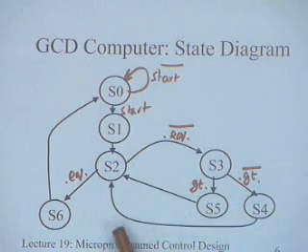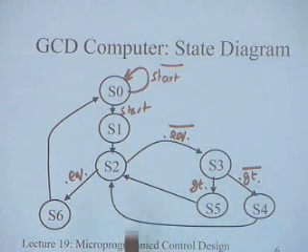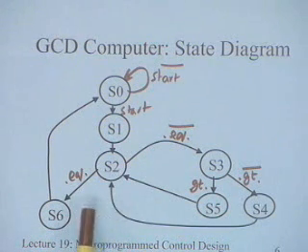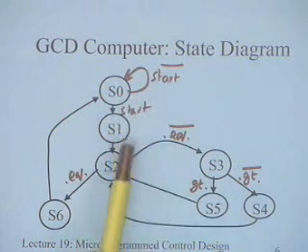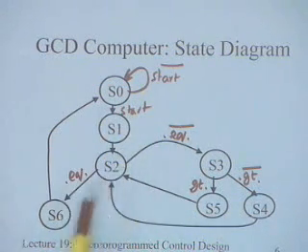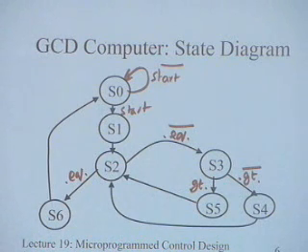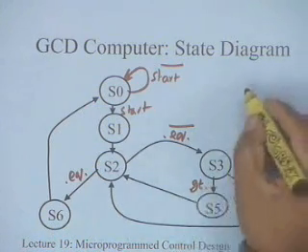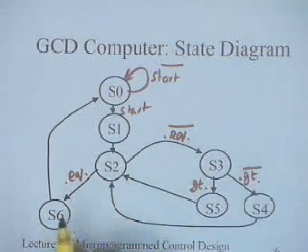Of course, sometimes if it is very critical in microprogrammed control also, there are mechanisms to do it, and we will talk about later on when we talk of sequencer designs, how we can support multi-way branching. But the typical microprogrammed control only does 2-way branching. And also, the reason I mentioned something about the state encoding is that I am going to translate each of these states into a microinstruction. Each state of the state machine is going to be one, and the way I have written my control signals, you can see what I am trying to do. Okay, this part will be clear from the next, we will come back to this.